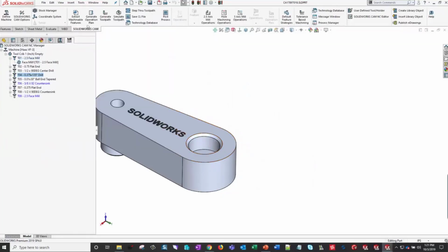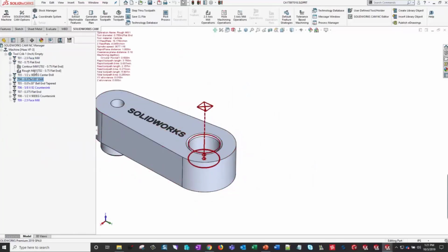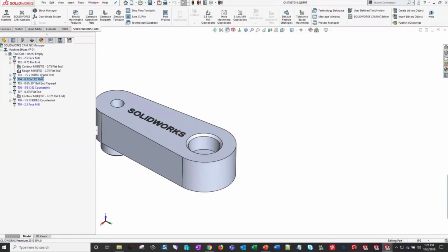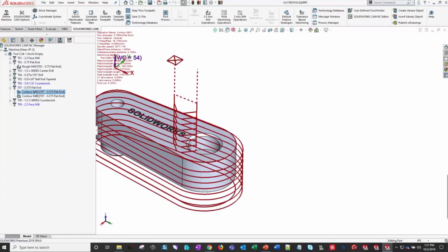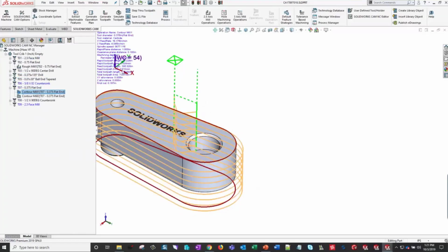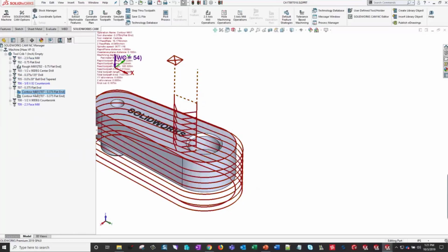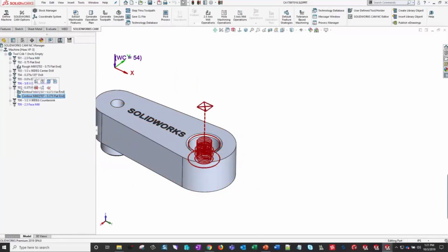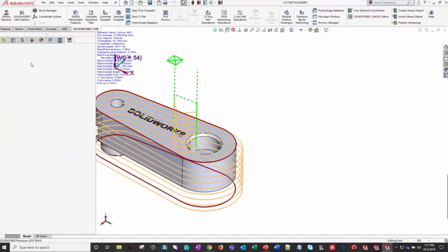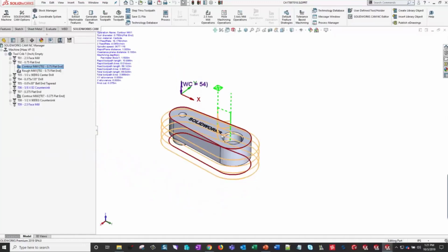Okay. And now, if we want to quickly do a tool change, another tip is, say I really want to use a different size, like this flat end mill. I actually want to grab this contour and drag it into here. I can quickly do that, and it already reran my toolpath. What I don't get is a preview if I actually edit it, but I can quickly drag and drop whatever I'm looking for. I'll just left click and drag this right back into there, and notice it updated my toolpath for me already.